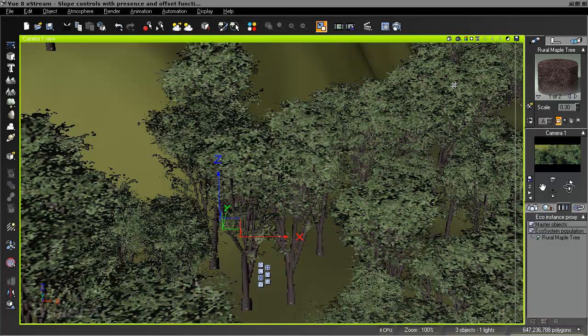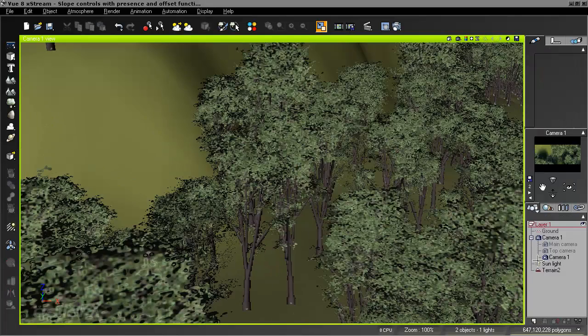So it does look like having that clear ecosystem layer with nothing on it was causing the issue. Just make sure that if you want to use the mode, there are no additional layers without any population on them, or that have a clear population, because it looks like at the moment that's interfering with this addition.